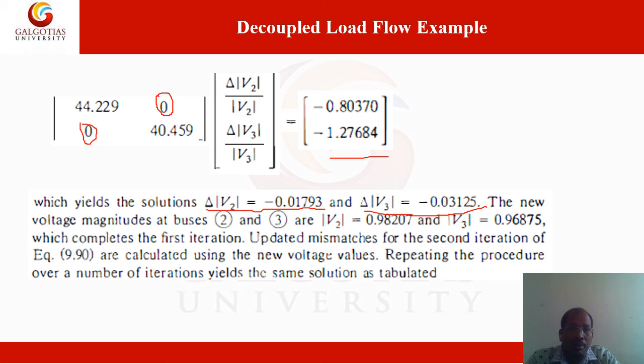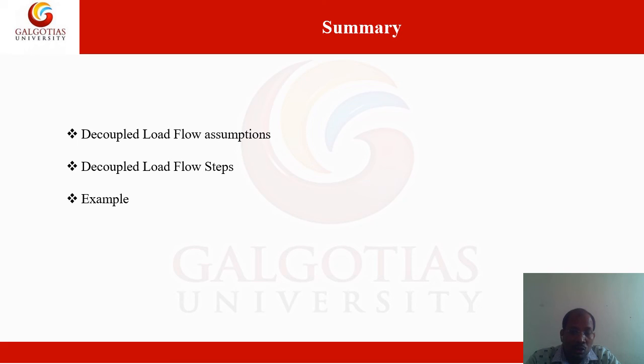So this is all about the decoupled load flow model. This is a very simple computational method. In this problem, J12 and J21 become 0, so there is less storage space needed. Only J11 and J22 have to be stored, otherwise the computational time would increase. So using the decoupled method, we can enhance the computational efficiency as well as reduce the computational time and space problem.